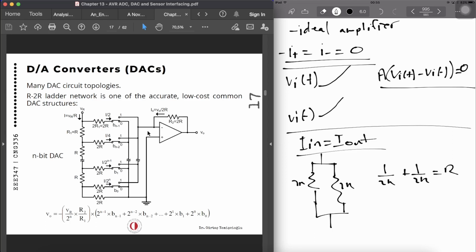Now, what does change is that this current was flowing through this branch. So you can notice how this current keeps splitting, right? We get the total current, VR over R over here, and then half goes in one direction, and this is 2R, and remember the other direction is also 2R.